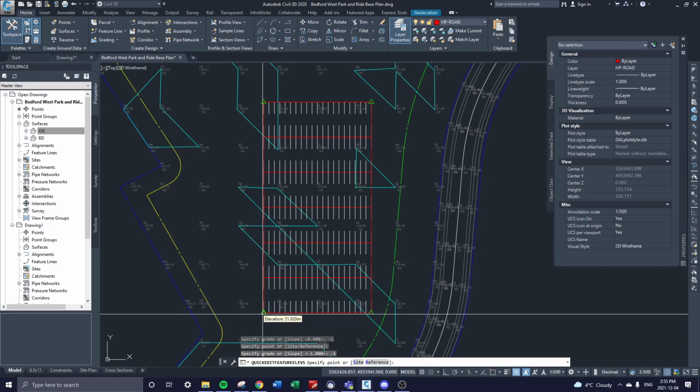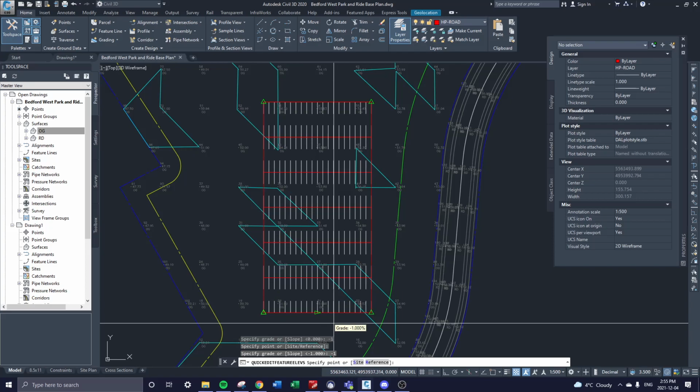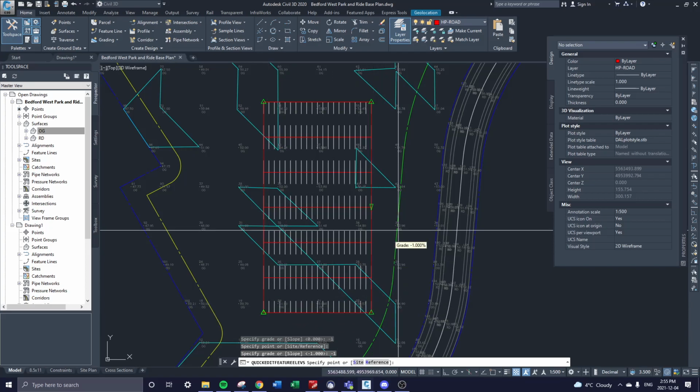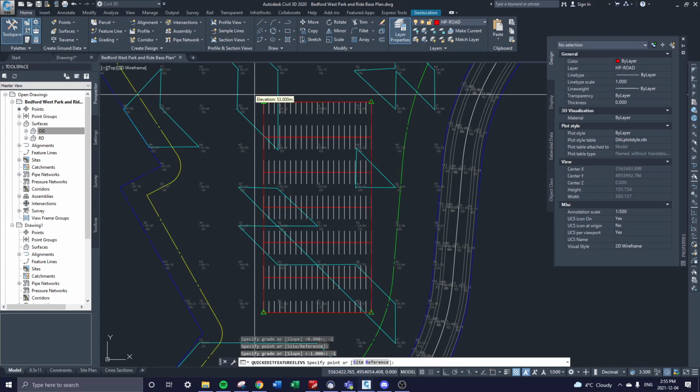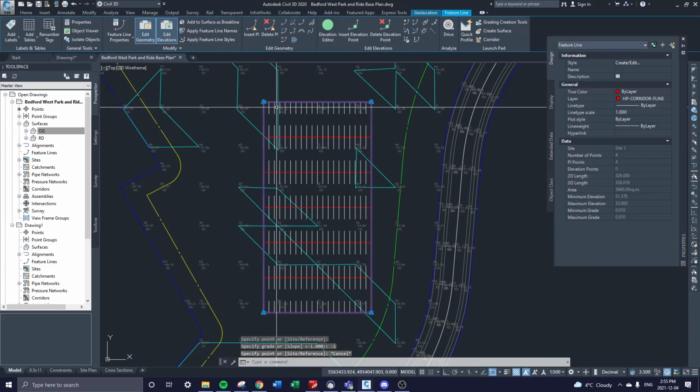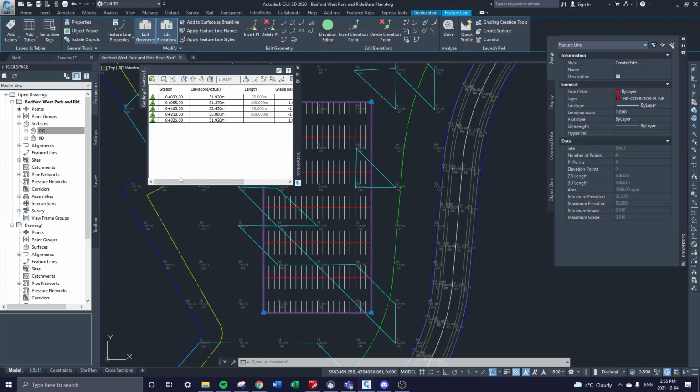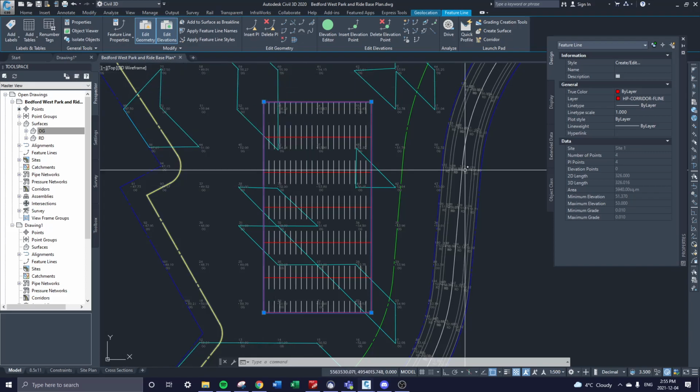So what is that elevation? 51.92. And that's at what? 51.37. Okay, so that's a difference. Just make sure that they're all kind of graded. Okay, so yeah, just to reiterate, this lightning bolt is a great tool, but if you prefer Paul's method, you can open up this window and you can change elevations here. You can change the elevations through these columns. They do the exact same thing.